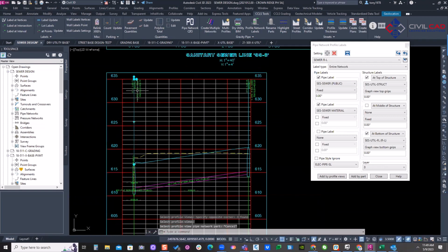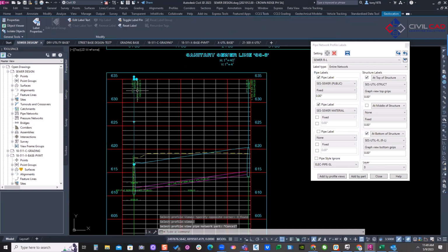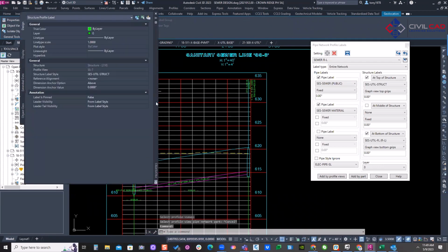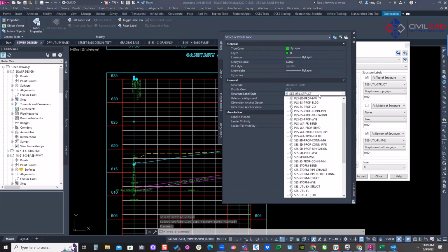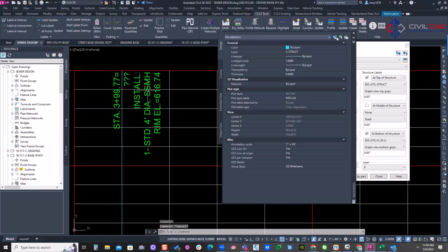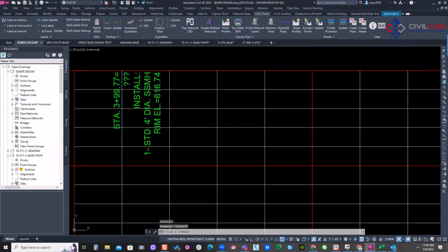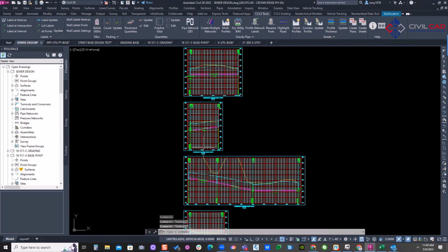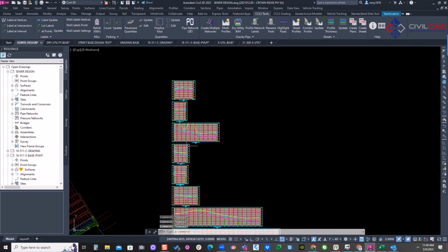Now you just need to swap the ones that need to be swapped. So maybe this one is now a location where 2 trunk lines or 3 trunk lines come into play. So that could be, you know, the one would have a reference, another alignment. There we go. Now you can click that other alignment. Typically, I'll change one and do match properties and just match properties the ones I need to flip or change. But as you can see, it's pretty easy.